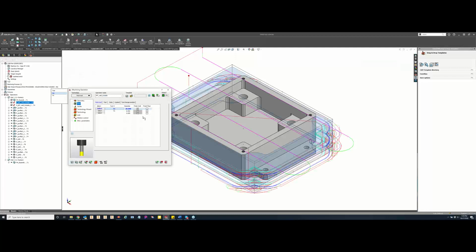Was that what I was supposed to show there, Greg? Yeah, I believe so. What's nice about it is that it's not sending in that second tool and just cutting one finished pass. If you're going from a large diameter tool to something considerably smaller, you are going to get over engagement. So iMachining automatically recognizes that the rest material is going to exceed the cutting angle the tool is capable of, and it automatically inserts those extra passes to make sure you don't damage that tool.